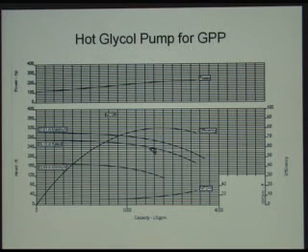And when we buy a pump, we would always have a minimum of 5% margin between the maximum or the minimum and the one that's actually going to be constructed with. Now the reason we do that is if it turns out that the process changes and needs a little bit more head between the time that we place the order and the time that the pump is going to be shipped, or if it's anticipated in the future the head might increase, this gives us the ability to just change the impeller out and get the additional head required for the process.